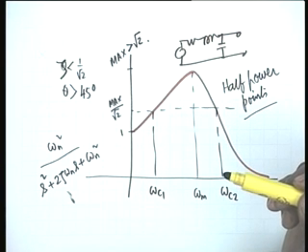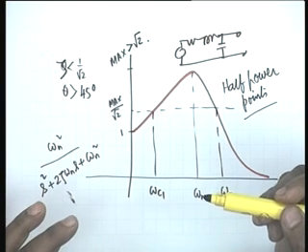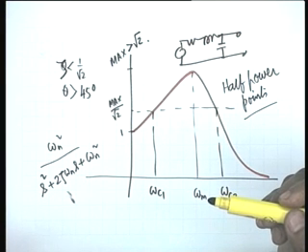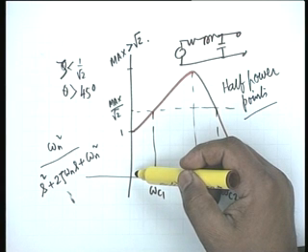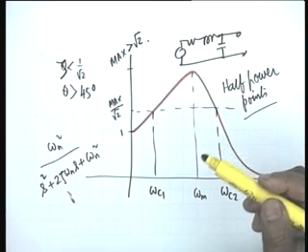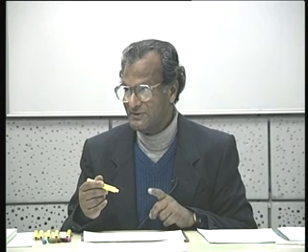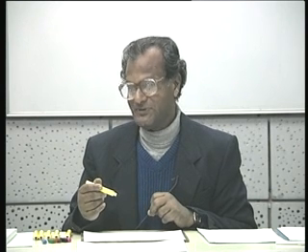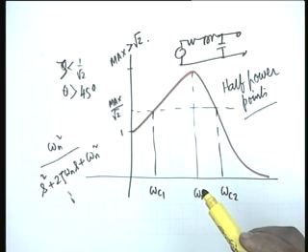It would not be so had we taken the voltage across the inductor. It would have started from the origin at 0. Is that clear? If we had taken the voltage across the resistor, then also it would have started from 0. It is because we are taking it across the capacitor that this peculiar situation arises.